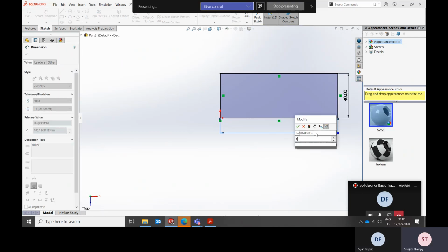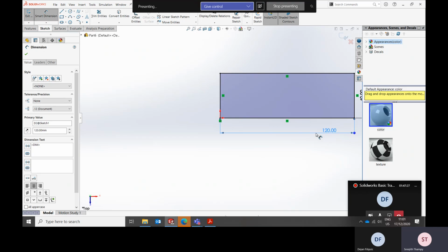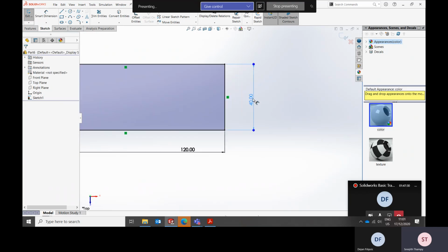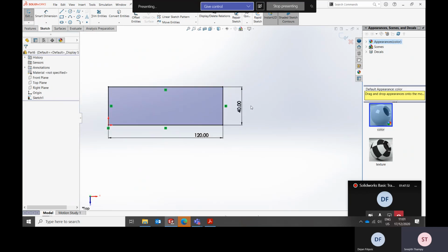You might have seen that I have just drawn a rectangle and I haven't given any dimension at first. For the first sketch, we can just make a profile and the sketch will automatically adjust to the scale of the first dimension being given. That's a feature in SolidWorks. So we have created our first sketch.